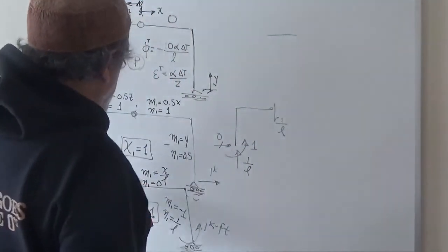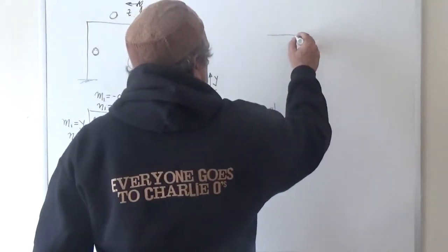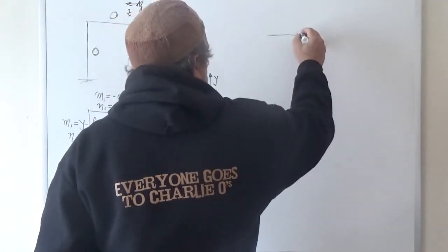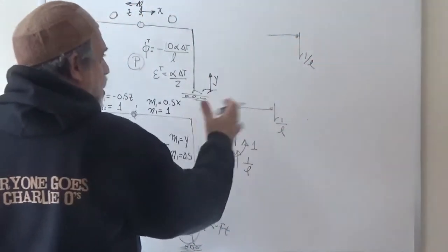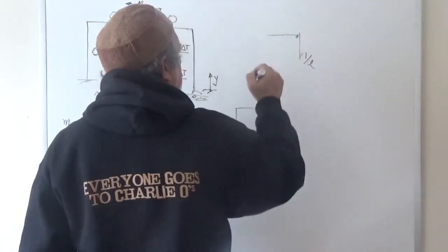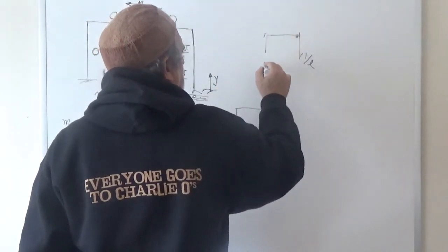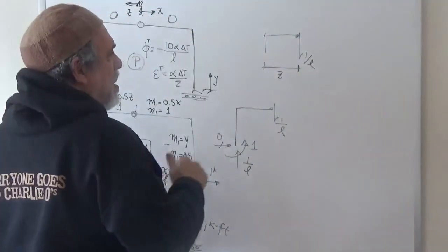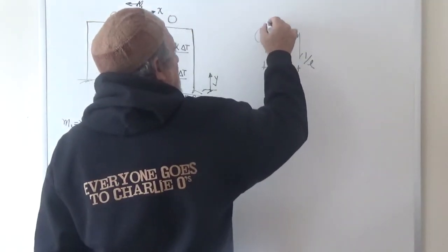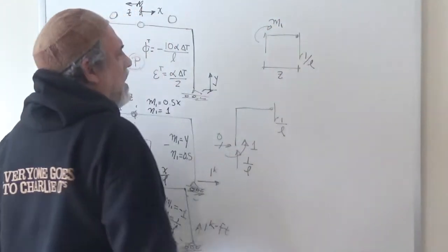So we've done this part. We're looking from the hinge to the left here. So we have 1 over L, which is that force, no axials, and we just cut over here. That distance from here to here is Z, as we've seen from this sketch. Our moment convention is necessarily this, and there are no axials.